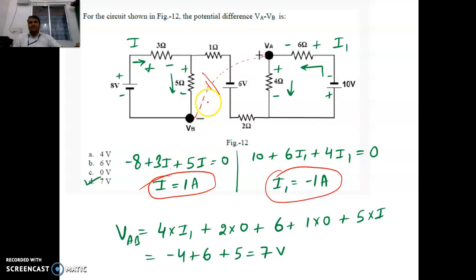Let me move from here, so that it is coming with a negative sign. So that's why I keep it minus AB also and make it plus. So I'm saying minus AB, so the entire thing equals 0. So that also is possible. I will write this is minus AB, this is AB, but I'm moving from this end. I will move like this, moving in this way, and then we will move this way, and after that again we come back to here. So wherever you start, you must reach the same point. So you apply this KVL in the closed path in the circuit, so it will come out to 7 volts. So that is how you can use the KCL.